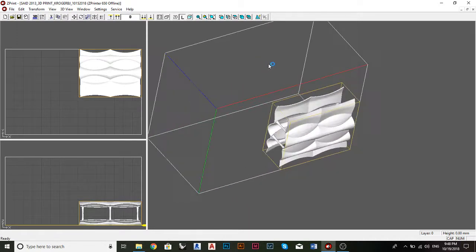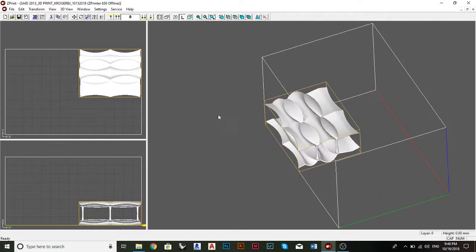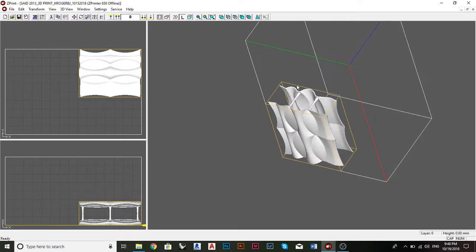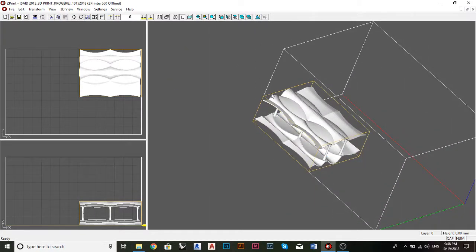Okay, so like Mara said, there's no black shaded objects. Anything that's black shaded and has no tone to it will not print. So that is an error, and that is something you will need to solve. It could be some naked edge, probably somewhere along some connection point that you'll just have to address.